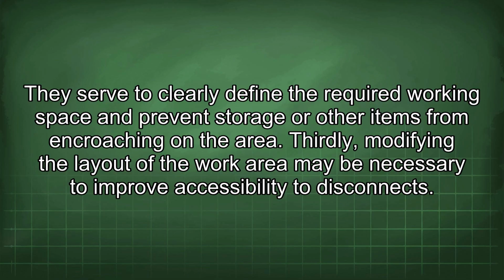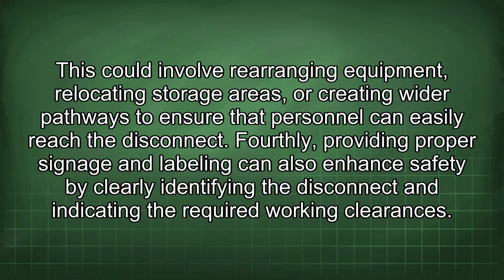Thirdly, modifying the layout of the work area may be necessary to improve accessibility to disconnects. This could involve rearranging equipment, relocating storage areas, or creating wider pathways to ensure that personnel can easily reach the disconnect. Fourthly, providing proper signage and labeling can also enhance safety by clearly identifying the disconnect and indicating the required